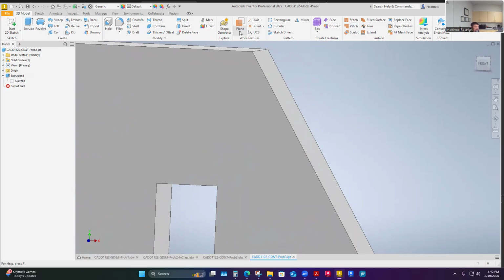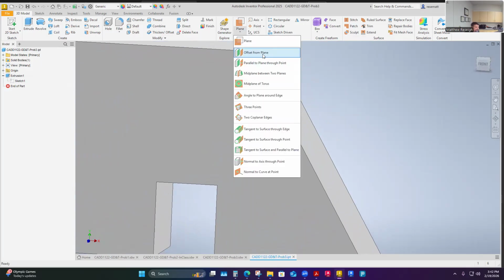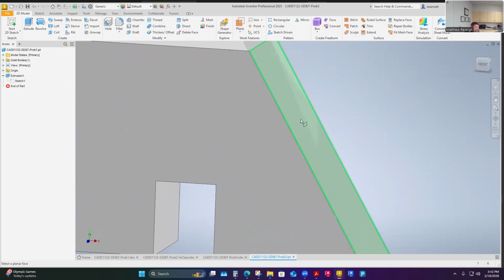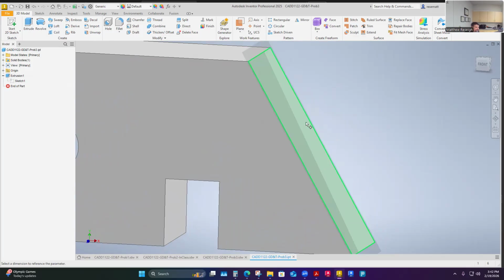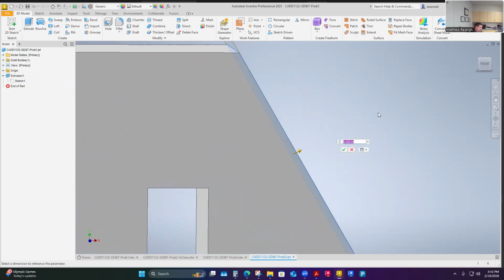And so what it does is if I take a plane, and I'm just going to offset a plane from this particular work surface. I'm going to select this as my surface. I'm going to offset it, not 10,000ths. I'm going to offset it 5,000ths in this direction and 5,000ths in the other direction from the theoretical exact place it could exist, like our model is the theoretically exact way we would like it.